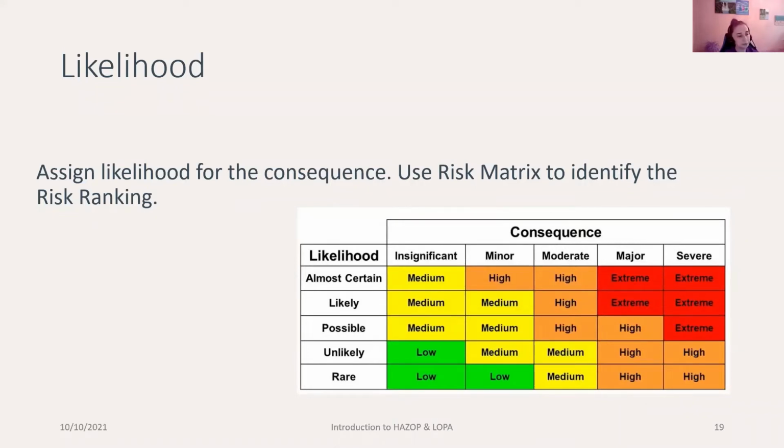Again, different companies have different criteria for that, but sometimes as soon as you go to one specific area, for example moderate for safety or environmental consequence, automatically it will need to go to LOPA. Even if you identify the safeguards here, it will still go to LOPA, and you don't even need to risk rank because this will be done further in LOPA.